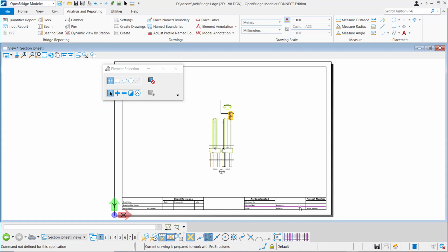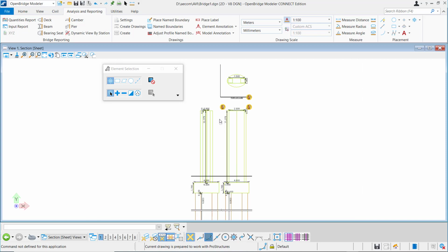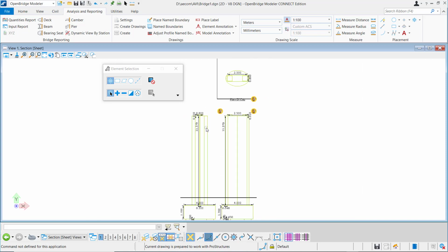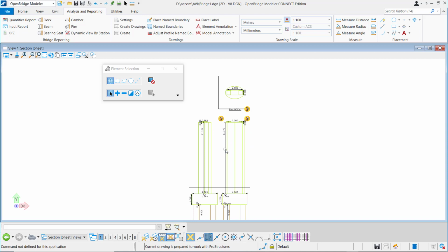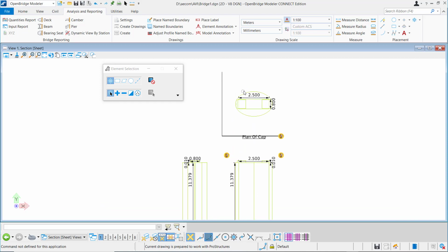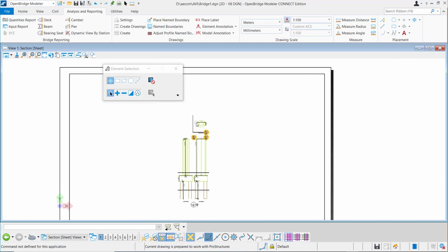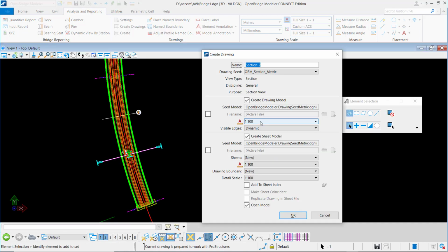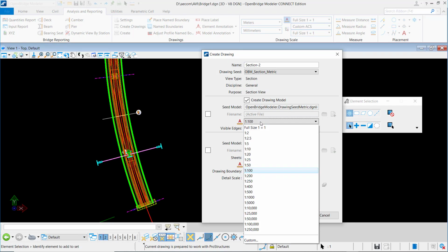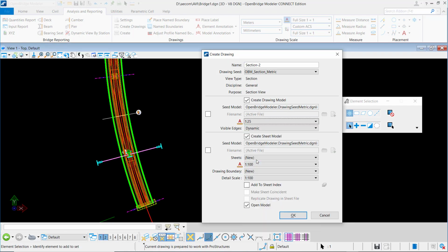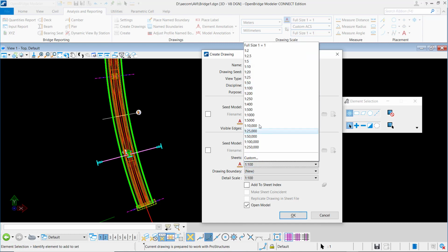Automatically, you see that our drawing is set with the 3 different views that we asked for, with all the different dimensions in the top, front and side views. We can also, with simple commands, add different dimensions that will be attached to the different elements of the pier, and so will be updated in case we have to define something differently.